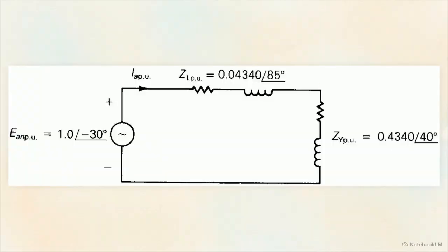This diagram shows the final single-phase equivalent circuit in per unit. Because we normalized the voltages and powers, the ideal transformer physically disappears from the math. We are left with a simple voltage source and a string of series impedances. With the entire grid on a common base, you apply standard circuit algebra, a basic Ohm's law calculation. Voltage divided by total series impedance will now yield the exact fault current for the system.